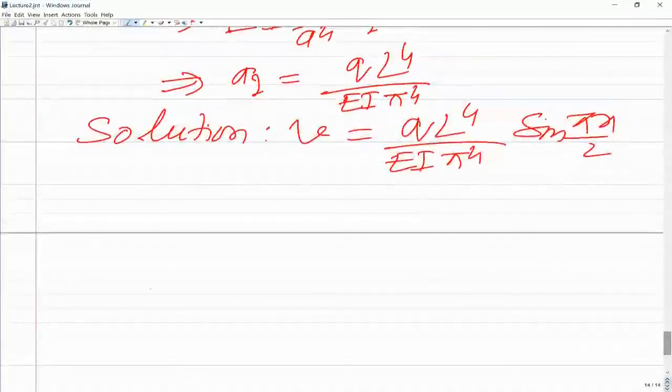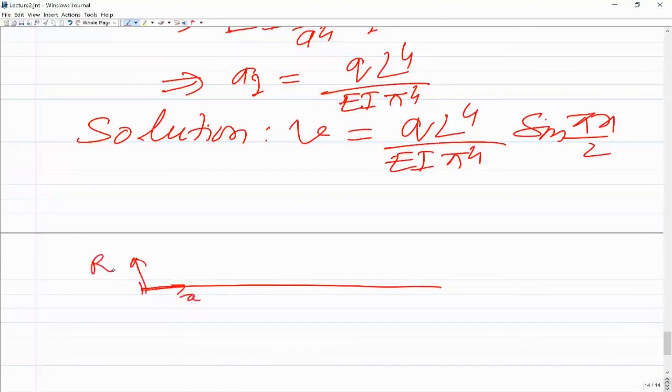Now, why we use these methods is, after satisfying the boundary condition, we got the approximate solution and then the residual. So in general, along the length, this is your x coordinate, and if you plot your residual R, it could be some function of x, throughout the domain, could be positive, could be negative, could be changing from positive to negative, so it can have any variation.